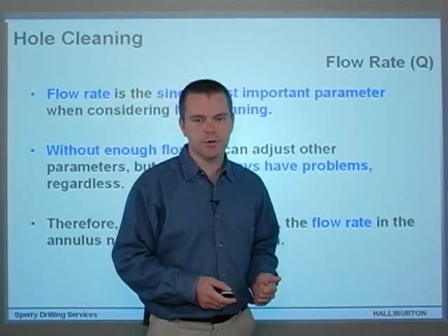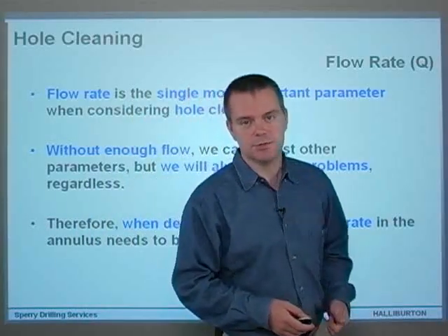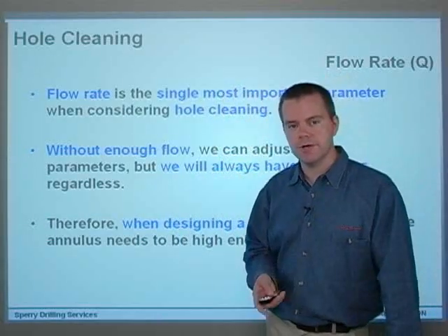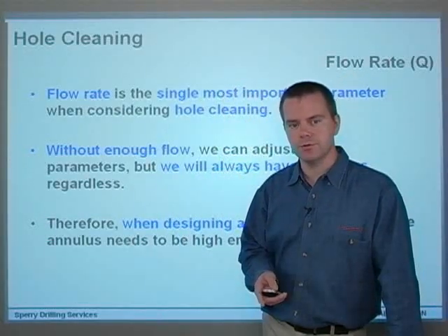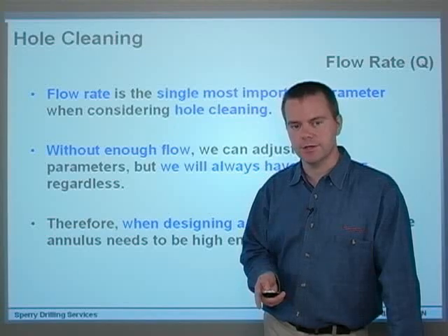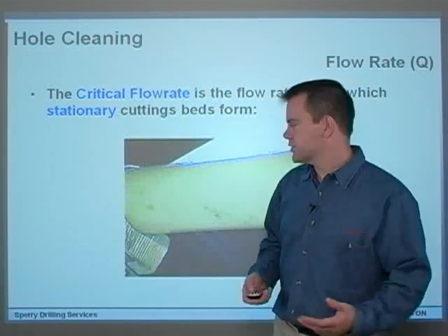When we're designing a well, the flow rate in the annulus needs to be high enough. That's something I want you to remember all the time when you're looking at a hole cleaning job. Flow rate needs to be high enough. So what flow rate is actually high enough?